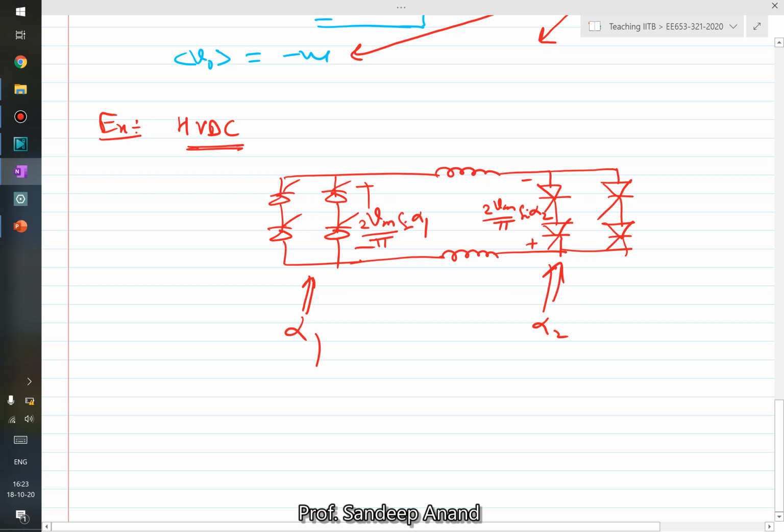Now this is a high voltage DC link, where you have two bridges connected far apart, and there is a line interconnecting these two bridges. Now what if you want to flow power from one bridge to the other bridge? Let's say in this direction. You want to flow power in this direction, current is flowing in this direction, right? You set the values of both the voltage sources just slightly different. Why? Because if you set them significantly different, then the current would become very large.